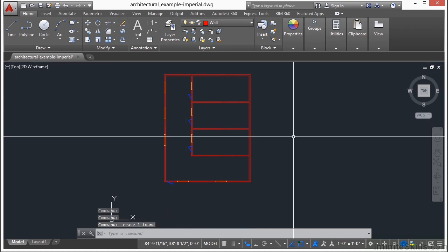When you turn off an object's layer, the objects are invisible, but they still hide objects when you use the hide option when you're printing or working in 3D. When you turn layers off, the drawing is not regenerated. When you freeze or thaw a layer, objects on the frozen layers are invisible, but they don't hide other objects behind them when doing 3D work.